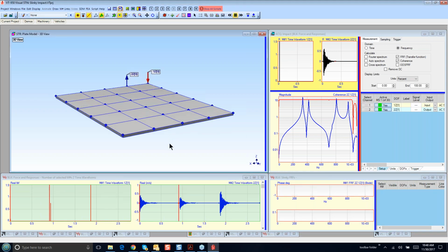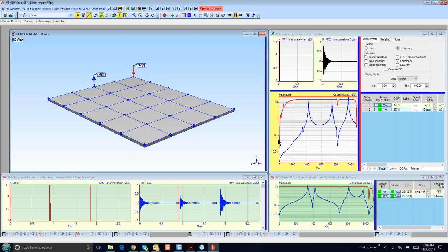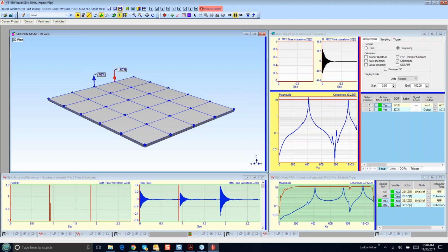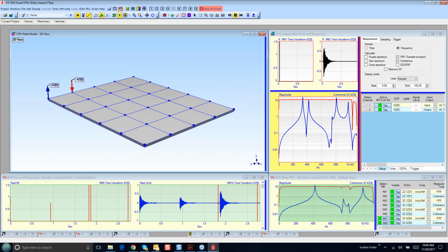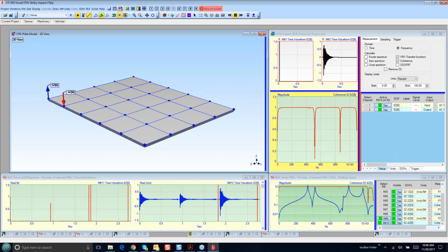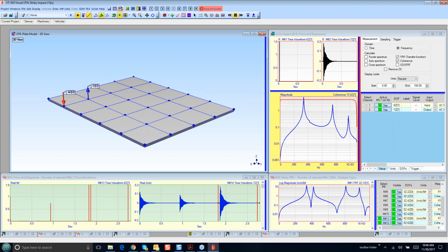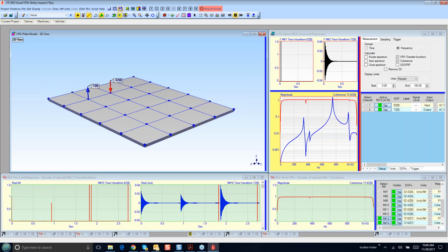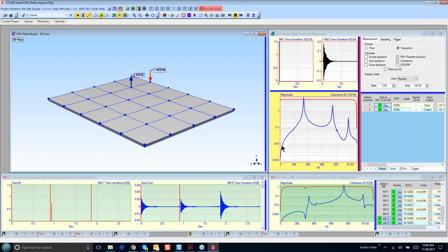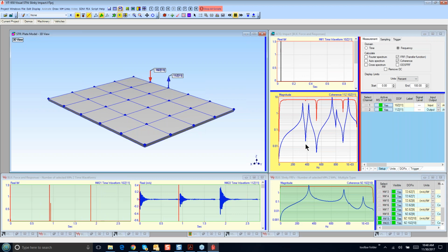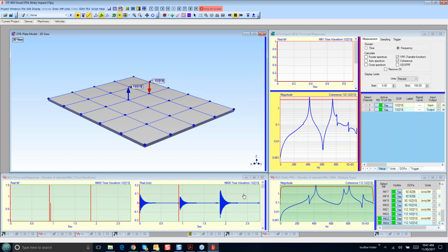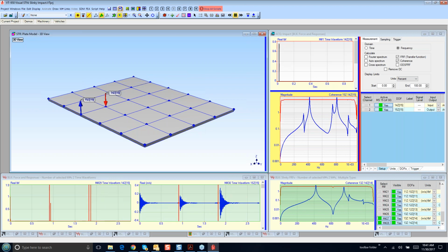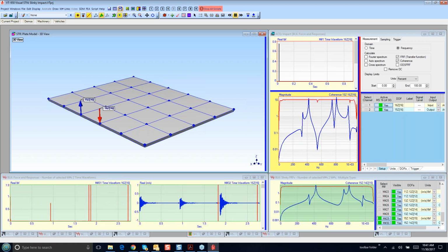Now what you're going to see going on here is the acquisition window is connected to the data block down here on the lower left, and it's doing 3 averages. It's actually averaging, you can see the cursor moving along there, taking several thousand samples of data out of the data block, calculating FRF and coherence. And then as it computes each one, it's accumulating them down in here into the lower right data block where you can see each measurement and its coherence overlaid being accumulated down there.